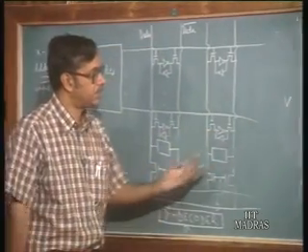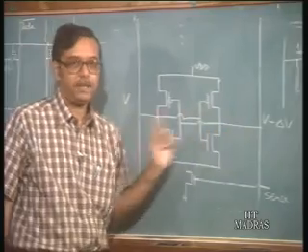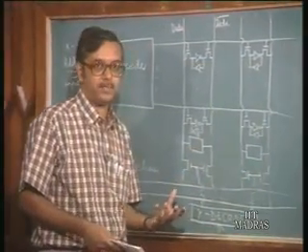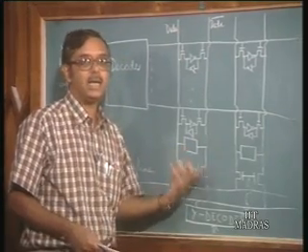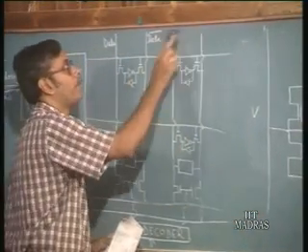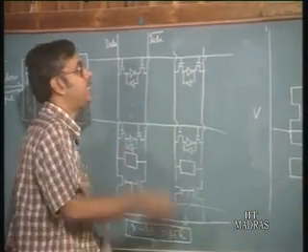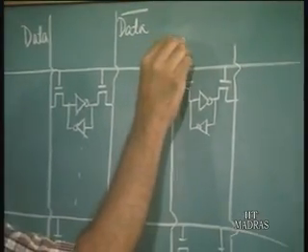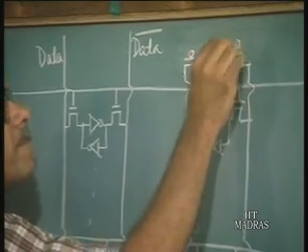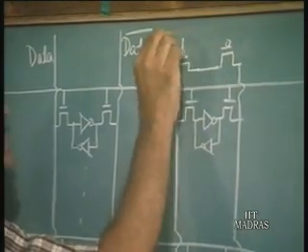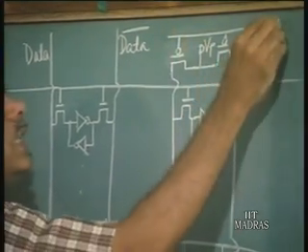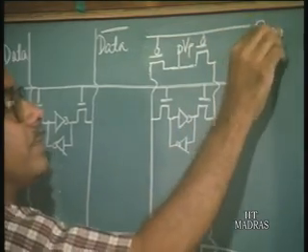The other thing which is done is, what we must do is we must initially have equal voltages on these lines. Okay. So, what we do is we do a pre-charging. So, both these lines, the data and data bar lines, are maintained in the pre-charged condition. So, what we have here is a pre-charge circuit, which is nothing but two transistors here. Say these are two PMOS transistors, and here you have a voltage Vp, which is the pre-charge voltage, and this is the pre-charge line.